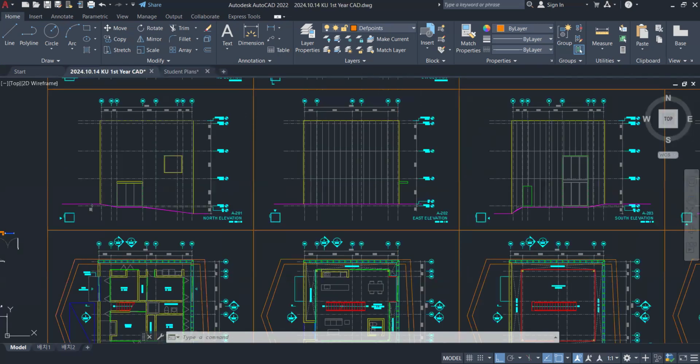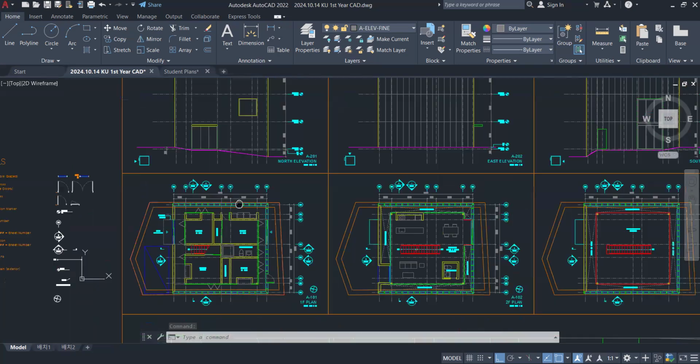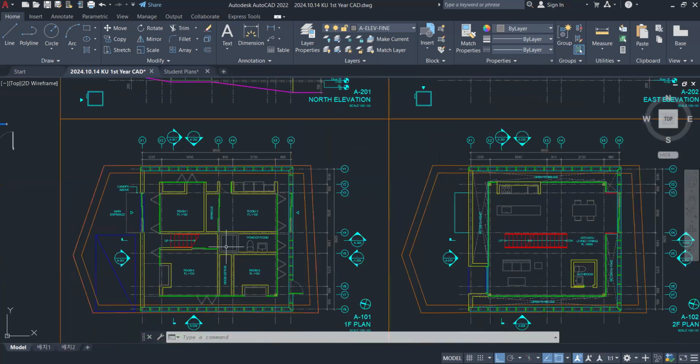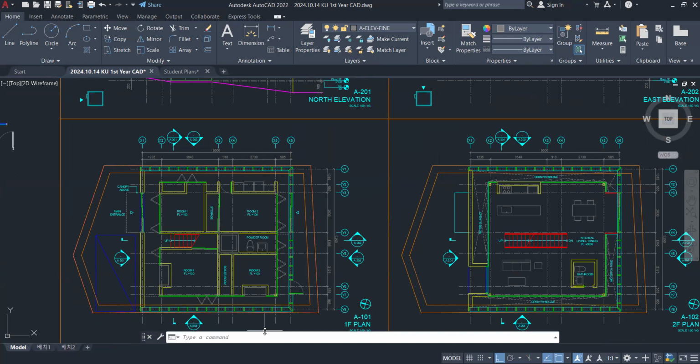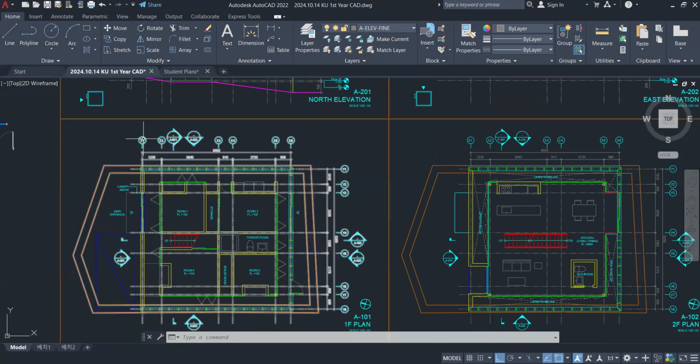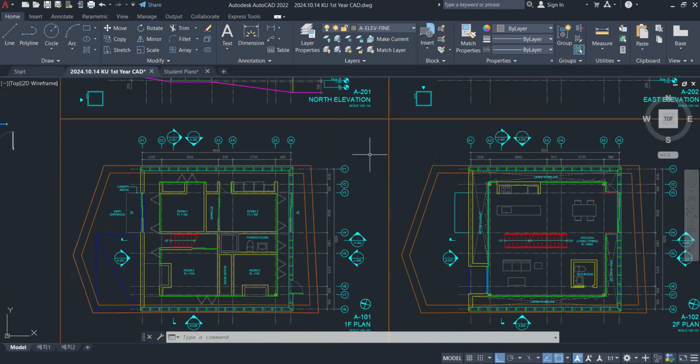Let's go back to the sauna house here. Note that measurements are only given with the grid lines. There are no grid lines on the left-hand side, and there are no grid lines on the bottom of the page. Because of that, we consolidate the dimensions. They always follow the grid markers. So you should pick two sides.